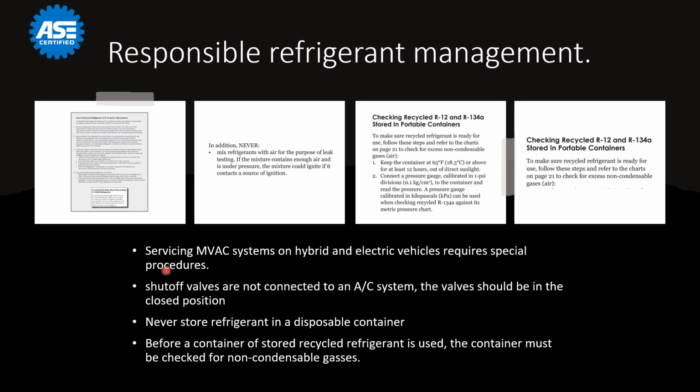So just little things like this that I noticed in the book, that we can create good habits for us as technicians as we're working through these systems. It also gives us a list of things we should never do when we're storing refrigerant, or when we're working with these systems, when we're servicing an AC system. One of the things that I noticed is to never store refrigerant in a disposable container.